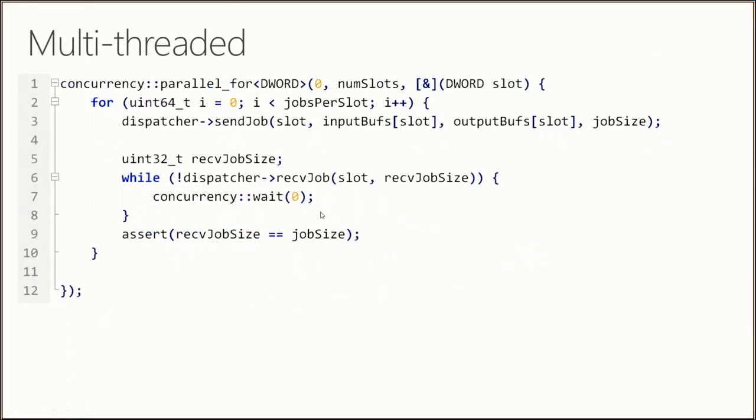One issue with the single-threaded technique is that we assume each slot computes jobs in lockstep, which means no slot can start a new job until all slots have completed a job. Also, job dispatch and waiting are sometimes on the critical path of the program. Although not shown in this example, it is common that data need pre-processing or the FPGA results need checking for correctness. So it is, in some sense, inefficient to put all jobs on the critical path.